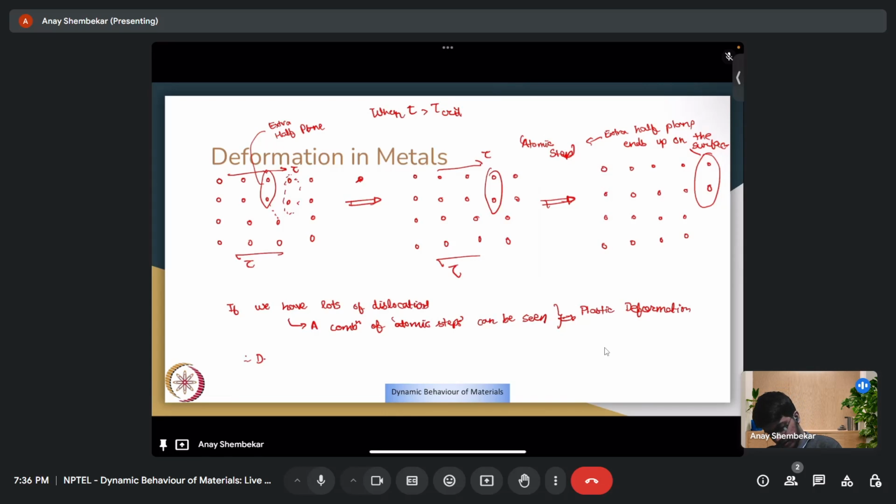As a result, you can think that ductility is due to plastic deformation, due to dislocations. So ductility and plastic deformation are more macroscopic concepts. What we hope to get clear on is how the underlying microstructure leads to a situation where you have dislocations, which eventually lead to plastic deformation, and that shows up as ductility in your uniaxial stress strain tests.